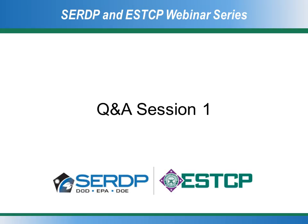But I will just say generally that karst and sinkholes have been very effectively tackled with resistivity, water or airborne, and particularly in Florida. There are many published studies of the use of the electrical resistivity method to image sinkholes, so it's a starting point. I would suggest that would be a candidate technology. But again, we would want to consider, before going to the field, doing some conceptual pre-modeling.